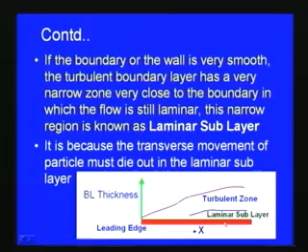So here you can see, say from here this x starts, and then this delta by x is with respect to this boundary layer thickness to the distance from this location to that particular location. And when we consider Re_x, the Reynolds number at this particular location where we consider the boundary layer thickness. So this, as far as a flat plate is concerned, is the experimental observation by various investigators.